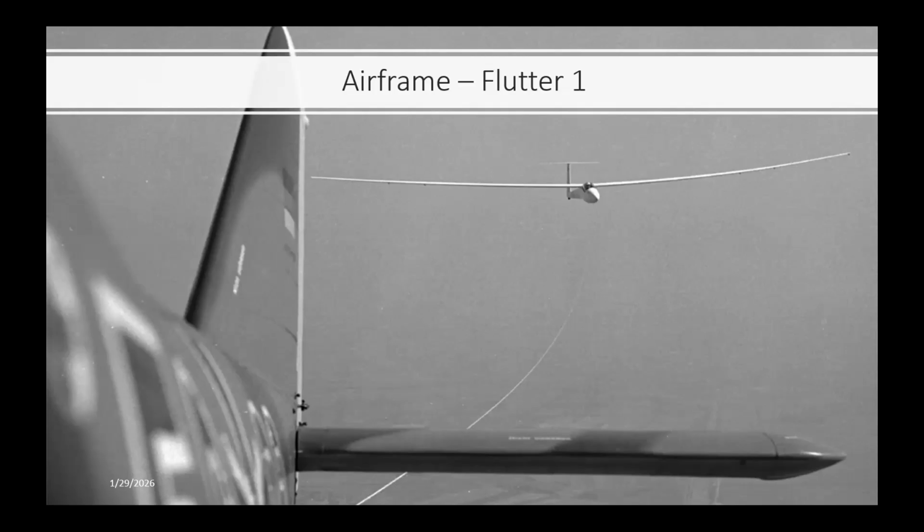During the flight testing, there was some flutter phenomenon, which I've got the video I'm going to show you here in a second. The flutter problems were eliminated by using aileron mass balance. And then long after the SB9 was no longer being used, they pulled the wings over, put them on the SB10, and flew the wings for thousands of hours.